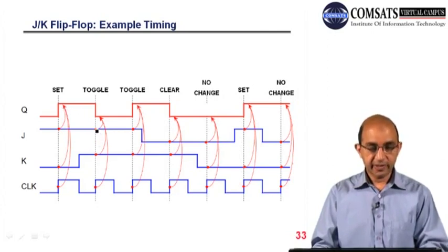And here this is a different scenario. We have 1, 1. Before, we had a race condition regarding the SR latch. Here we have something new. With JK 1 1, you can see that we have Q 1. So here we have a toggle, from 1 to 0.